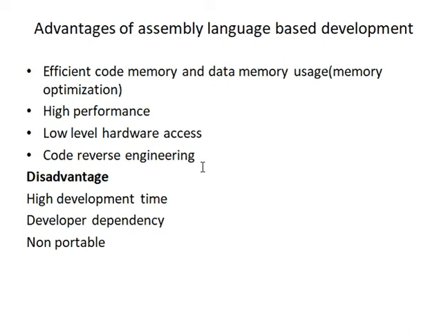Reverse engineering is a concept wherein from your converted hex file, you use a disassembler, which is a program used for analyzing the mnemonics from the hex file. You can pass the input to the disassembler, and you can visualize what the mnemonics are. Using these mnemonics, you can change them, and also you can do the reverse engineering in this case. So that's reverse engineering, and you can directly change the firmware whenever you require, but it requires intelligence too.